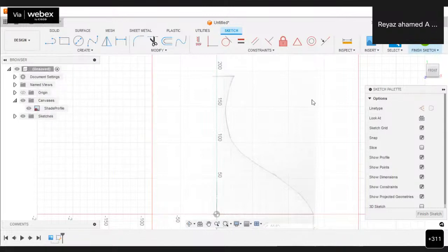See, if I click on sketch and then click on the plane, a new tab called sketch appears. In this sketch tab, only the tools needed to create a sketch are available: line, arc, rectangle. With the help of these, you may create different entities of sketches. And then there is an option called modify. With the help of the modify tools, you may modify the sketches created here.